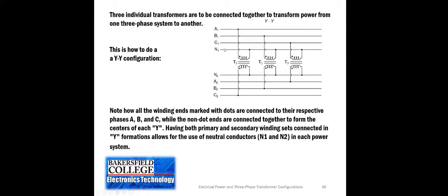So phasing is critical. If it's wired up incorrectly, then those voltages will not be equal like they should be, but one voltage will be greater than the other. And in addition, it's going to change the amount of current that flows through the coils. So that will have the additional disadvantage of putting more load into the transformer itself.